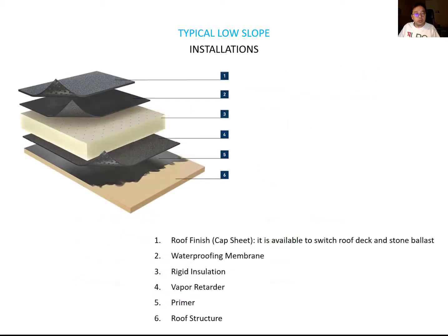So option 2 is an example here, for a better understanding of this diagram. The first one, you need the substructure, which you can see over your roof, and then you add the primer for the vapor barrier here. Then you need the exterior rigid insulation outside, and to protect the insulation, you need the waterproof membrane. And here you can do the roof finish.